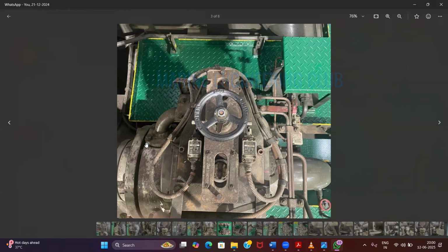Okay, slow turning is only for safety purposes. Suppose within that 30 period mark, if you press standby and something has happened inside your engine, you should be able to protect your engine, isn't it? Yes, sir. So that is why the slow turning valve is given. Okay, normally it is there on all ships, slow turning valve.